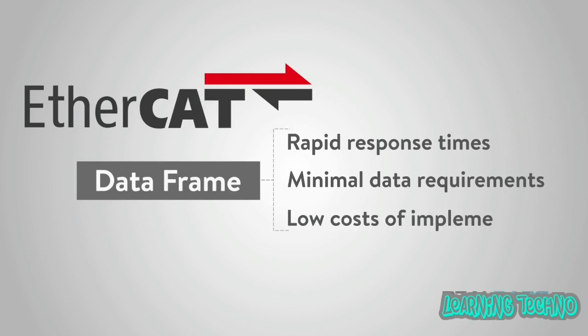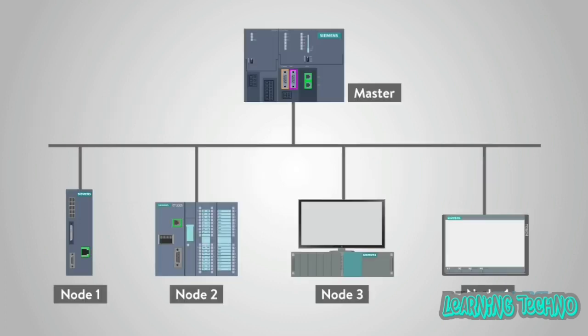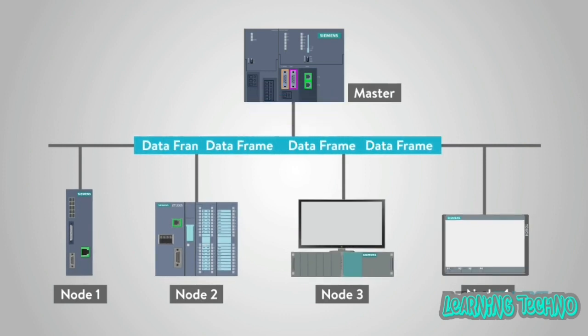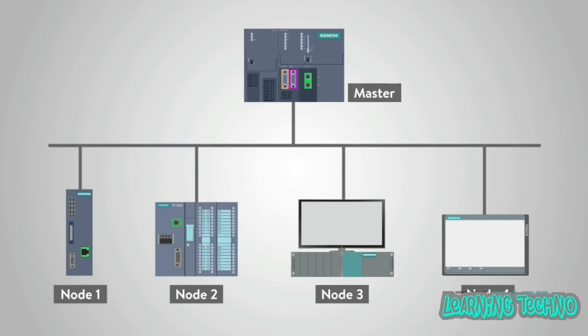and costs for implementation. Ethernet is not a practical solution for many industrial applications, as it routes frames of data to and from a vast number of separate addresses, individually, where the data may be something as simple as a single register to obtain a real-time analog reading. This node-specific routing requires massive bandwidth, as the data packets are only moved when the master or client requests the data.